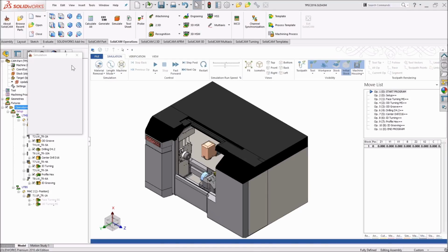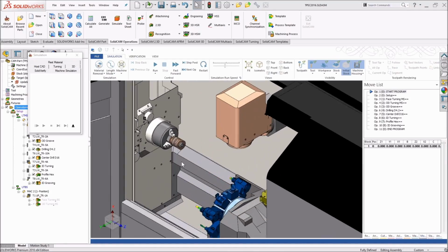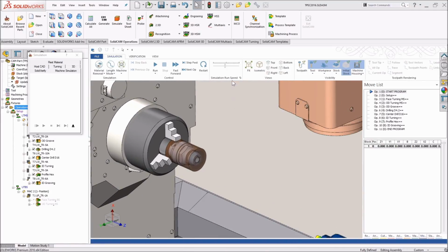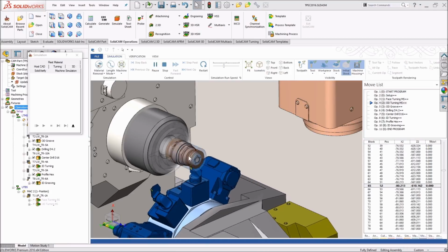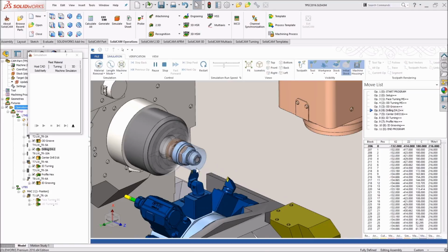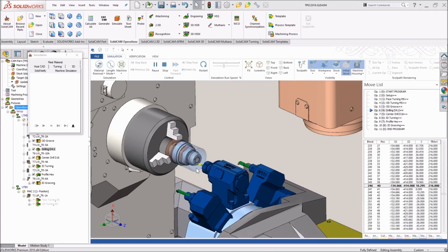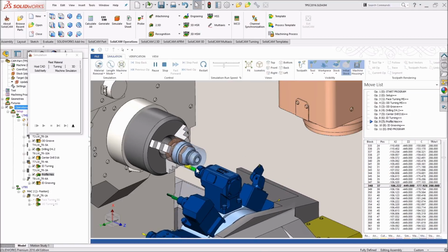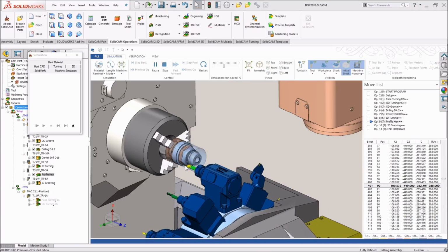and I'll just zoom in over here. What we have here is a pretty standard way of machining. It's just face turning, outside turning, some grooving operation, and drilling with the C-axis, internal turning, as well as hexagon machining using the C-axis motion.